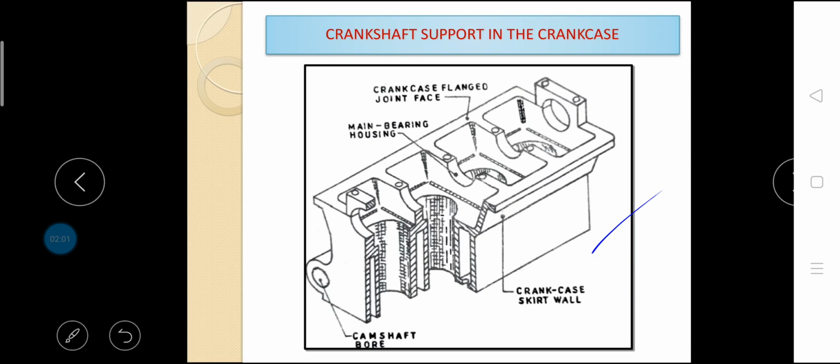The individual cylinder construction, on the other hand, has its own advantages. Replacement of a single cylinder casting is less costly than replacing a multi-cylinder casting. Because of the lesser weight of individual cylinders, handling during repairs is easy. In case of air-cooled cylinders having fins around them to increase the heat transfer area, it is easier to adopt individual cylinder construction than to cast en bloc.